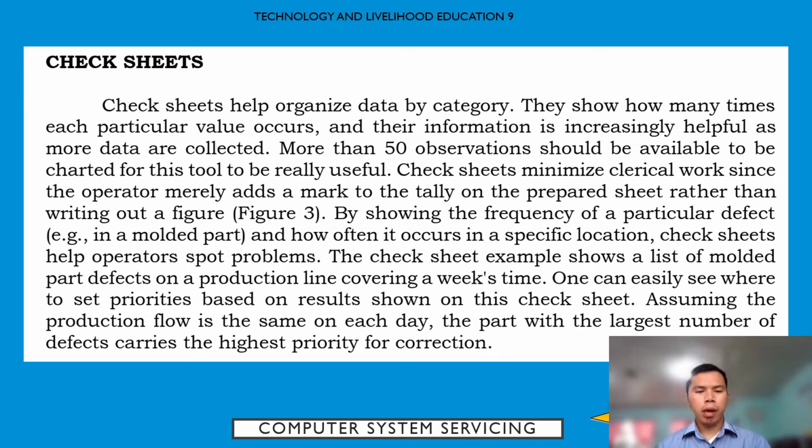Next is, meron po tayong tinatawag na check sheets. Check sheets help organize data by category. They show how many times each particular value occurs, and their information is increasingly helpful as more data are collected. More than 50 observations should be available to be charted for this tool to be really useful. Check sheets minimize clerical work since the operator merely adds a mark to the tally on the repaired sheet rather than writing out a figure.